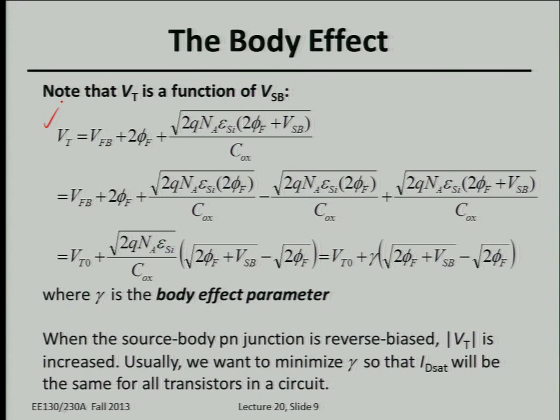In most cases of MOSFET operation, people just ground the source of the MOSFET, but the threshold voltage can be modulated by the substrate bias you apply. If you draw the MOSFET like this, say an N-channel MOSFET with a P-type substrate, in most cases you ground the source and apply a higher bias at the drain side. This is your VG, and this will be your substrate bias.